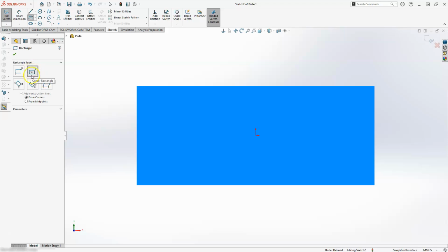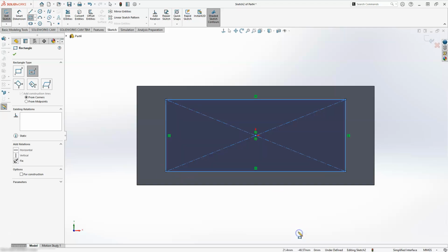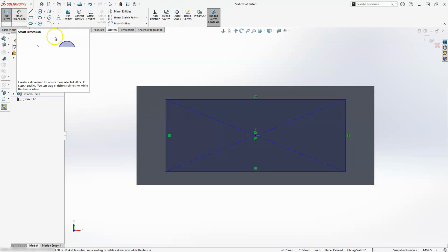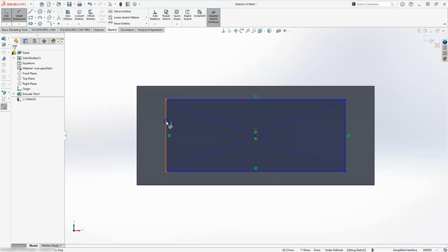So, I'm going to go ahead and specify, and you can see that number 1 is telling me to specify the center, which is going to be located here. And then I need to specify the other parameters of it. So it looks like it's sitting right about there. Let's hit the escape button, and then let's put the dimensions on it. So let's go to dimension here. And this has an overall height dimension of 30.